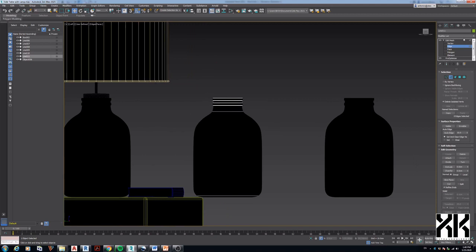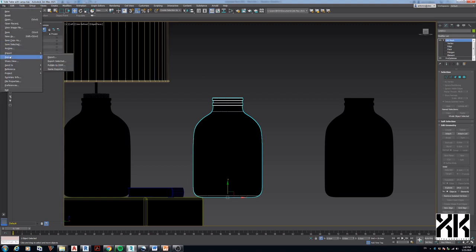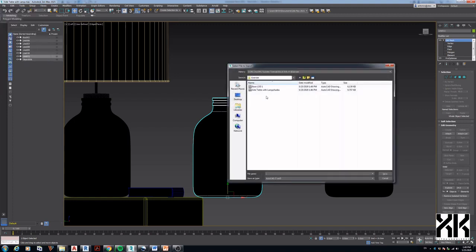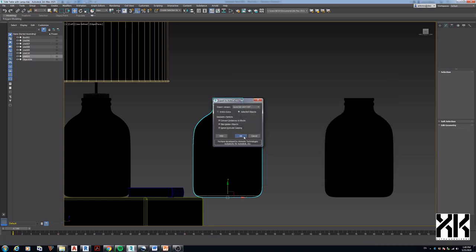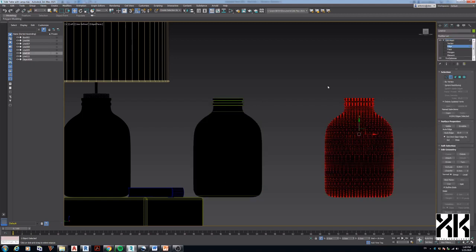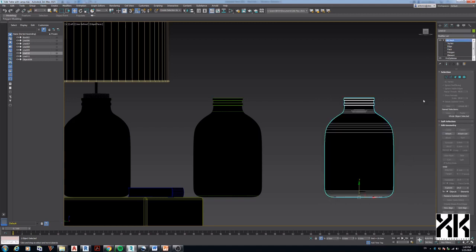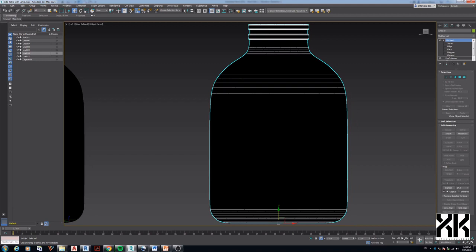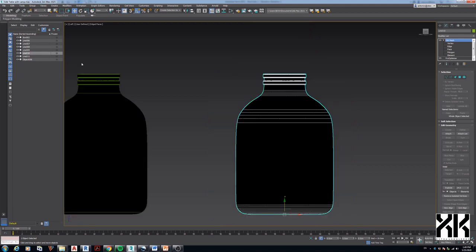The object is more defined compared to the first one. Export this object and name it Base LOD2. Then set the Auto Edge of the last base to 5, click the Auto Edge button, and deselect the object. Voila! It added more definition. Export and name it Base LOD3.